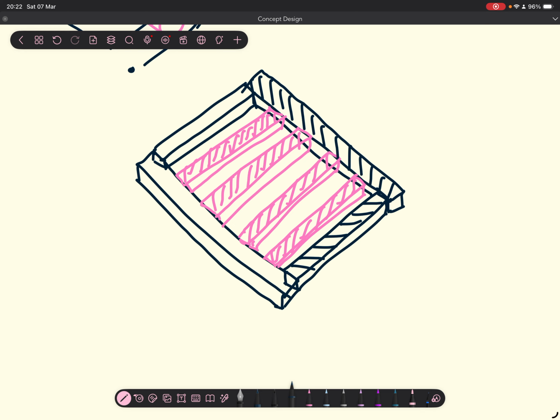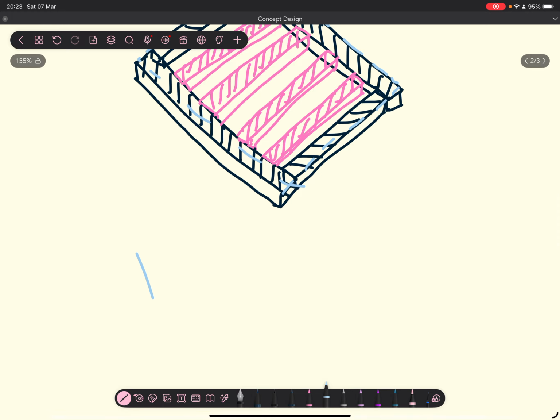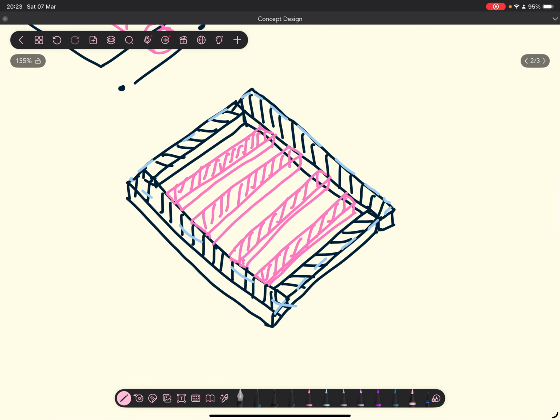of the funicular. Another reason why you'd want supports in the middle is if you're going to have some type of flooring. So if you're going to put a floor, like let's say you put a big steel sheet as your floor, that sheet is going to sag in the middle. So in order to prevent that, you need to put supports.